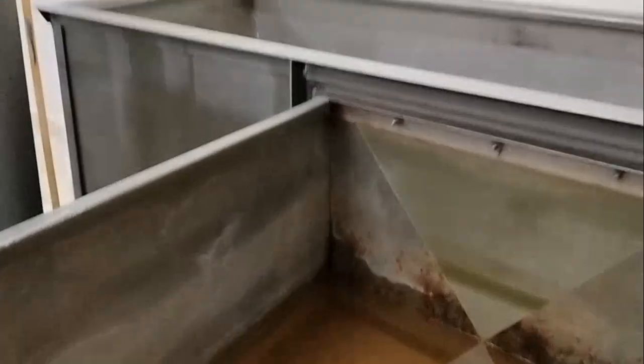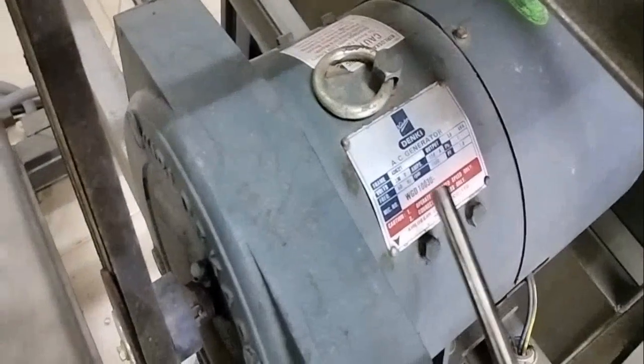Initially we have to set this scale to the zero level, which means we have to set this needle at the water level in this column. In this experiment, the load is applied by this AC generator. The load acting on the turbine is by the AC generator, using 200 watt bulbs. In the Pelton wheel experiment, the load acting on the turbine was by the brake drum, but here it is the AC generator.